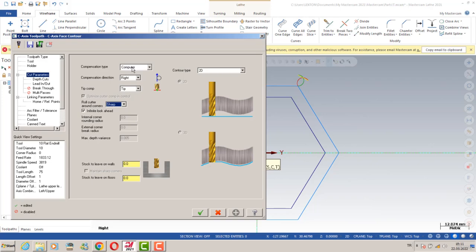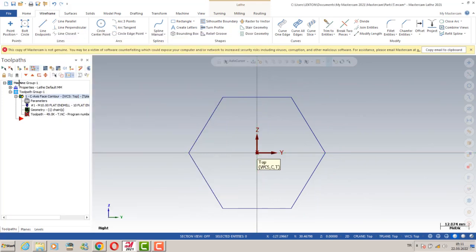If you would like to calculate your tool diameter offset in your CNC, that is another option. So of course, you need to turn to the control options here, and then we can organize it. We can turn to the computer options. Of course, at that point, we also need to be careful about our compensation direction.